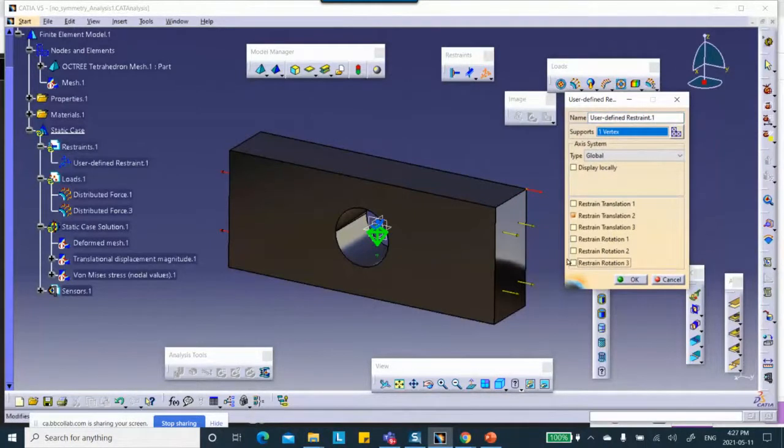solid elements have only 3 degrees of freedom. So that corner point does not move in direction X, Y, and Z. These things are irrelevant. You can check it, uncheck it. It doesn't matter. For solid elements, it's irrelevant. Okay, but don't check it. So that point is not going to fly away. It still can hinge about that point. It can spin about that point. So fine.